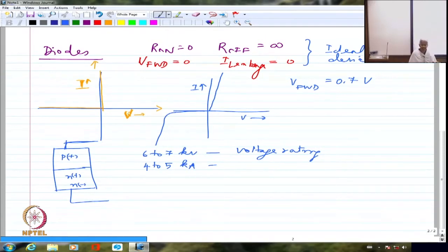So that's all right. Whereas when you work with a 15 volt circuit, 0.7 volts itself is a big deal. So you definitely would not like to increase the voltage drop any further. Then it is far from being ideal. So these diodes can have a voltage drop of almost 2 to 3 volts most of the times.